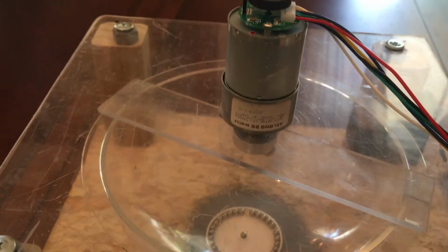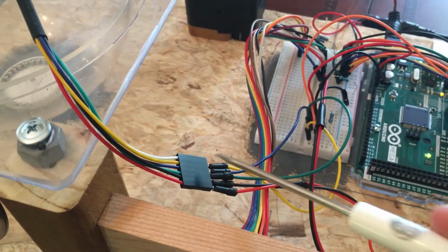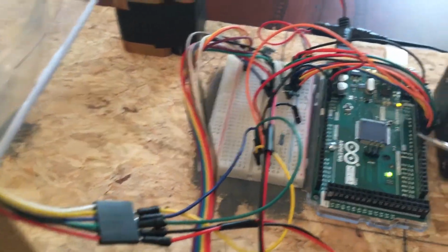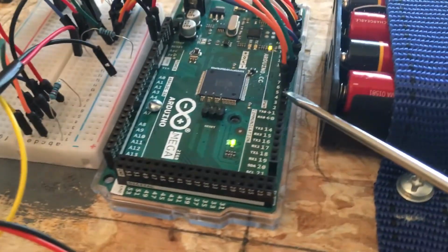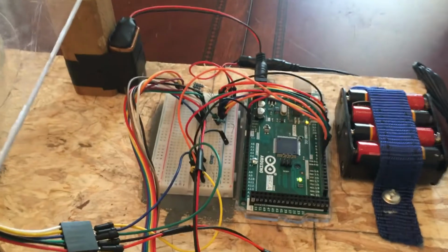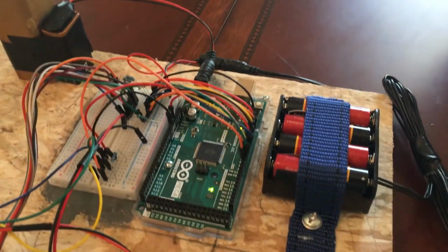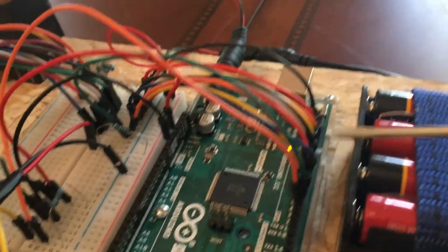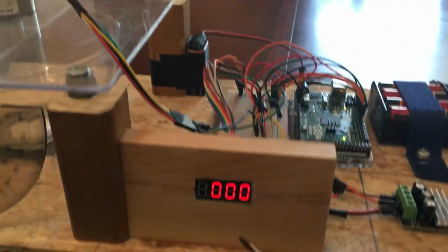The amount by which the magnetic field is disrupted can be measured and actually turned into an RPM value for our motor. The motor outputs its data through this yellow wire, which is connected to the digital pin 2 on the Arduino board. This is where it reads all its digital data, and we can calculate our RPM from. Digital pins 3 through 13 are used to power the LED 7-segment display.